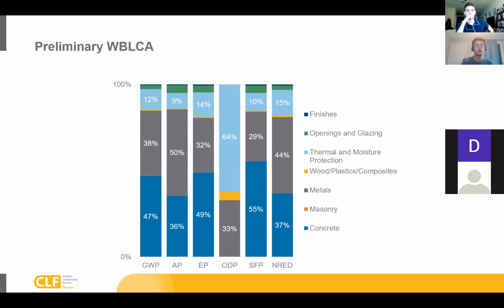So in lieu of EPDs, our approach is generally, let's put a maximum cement content and let that be informed by the NRMCA regional average. The National Ready Mix Concrete Association has average cement contents and cement impacts broken out around the US. And so we use that as a benchmark and then understand, okay, I think we can achieve below this. And then we put that in our specifications.